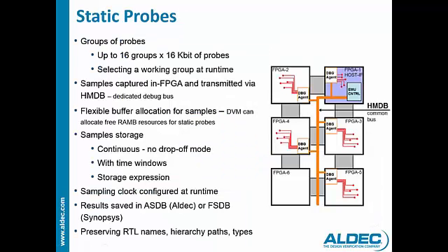So talk a little bit more about static probes. As mentioned, the static probes are similar to Xilinx ChipScope, which is like an on-chip logic analyzer. You have groups of probes, up to 16 groups, and each group contains 16 kilobits of probes. At runtime, one of those working groups can be selected for emulation.